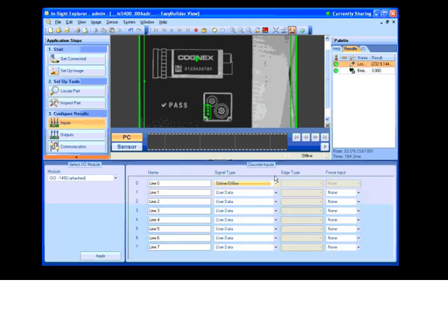I don't have something hooked up to my line 0 right now, but as I go online here, you'll notice it's looking for a discrete input into line 0 in order for it to go online. I don't have a hardwire to that right at the moment, but that can be remedied later. So that's our input functions.